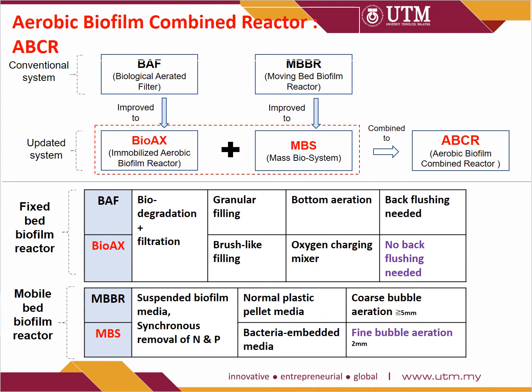In comparison, the conventional BAF only uses granular filling, but in the BioX we use brush-like filling. The main advantage is that it doesn't need backflushing to remove the extra layer of biomass. For the MBBR, the introduction of MBS is because we use embedded bacteria in the media, and the aeration also uses